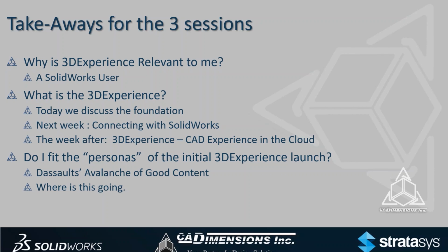Yep. You and I have been using SOLIDWORKS for so long. You have to think about those who never learned SOLIDWORKS, because if it's a school, they're starting at the beginning. When you clear your mind and get into XDesign, they took everything they learned from SOLIDWORKS and made it easier. A simple example: I'm going to do an extrusion in SOLIDWORKS, I have to click a different button if I'm cutting or adding material. In XDesign, I'm doing an extrusion, and as I'm doing it, am I adding material? Am I taking material away? Am I making a surface? The interface is very similar, but so much simplified and much more organic. It's going to be a heck of a lot easier to learn from ground zero.